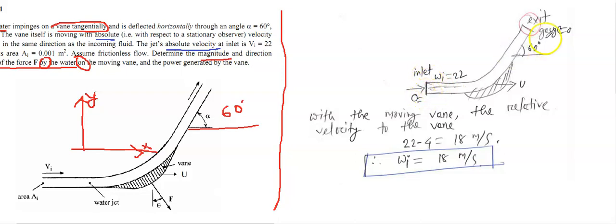This is the inlet, this is the exit or outlet. At the inlet and the outlet it has the gas pressure, so that means zero gauge pressure. This is the vane, this is the velocity u, and the direction creates a 90-degree angle here. The inlet velocity, we say this is Wi. We are using this notation W, and definitely for the outlet it should be Wo.